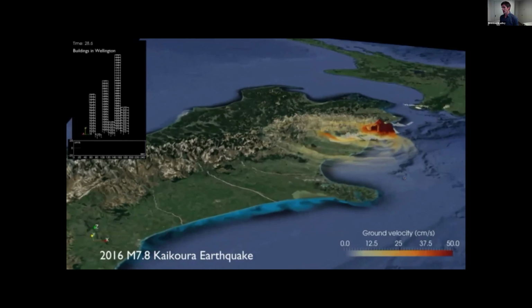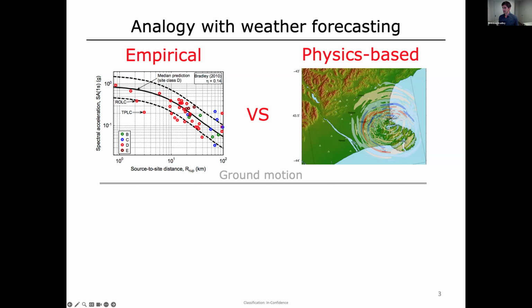So the ground motion simulation was done from data collection or from theoretical predictions? Yeah, I guess a combination of both, in the sense that, strictly speaking, we are solving the 3D wave equation for a viscoelastic or nonlinear plastic material. Ultimately, in that regard, it's just a model, but clearly there's a lot of important work and effort to validate those models to make sure that they reflect reality relatively accurately.